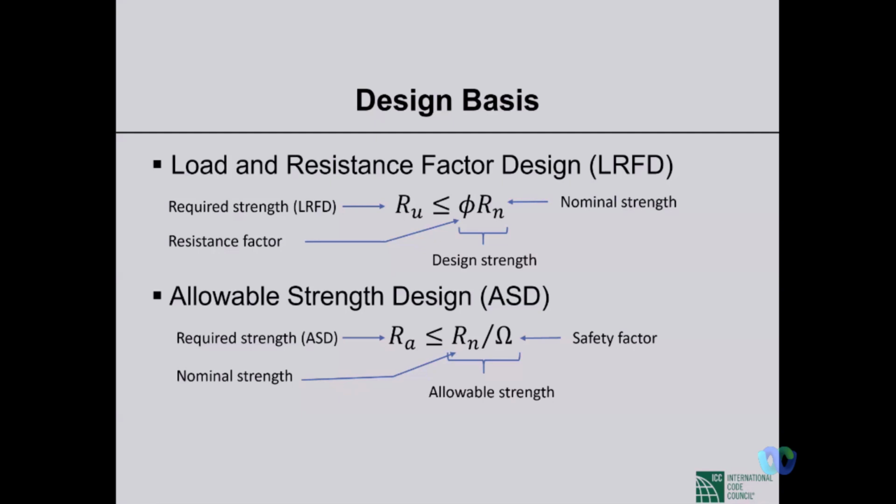So we increase the load, assuming the uncertainty of the loading in the extreme cases, ultimate limit state. So we increase the load and we calculate capacity, the inelastic capacity, and assuming the uncertainty of the material properties, we reduce it. So that is LRFD.